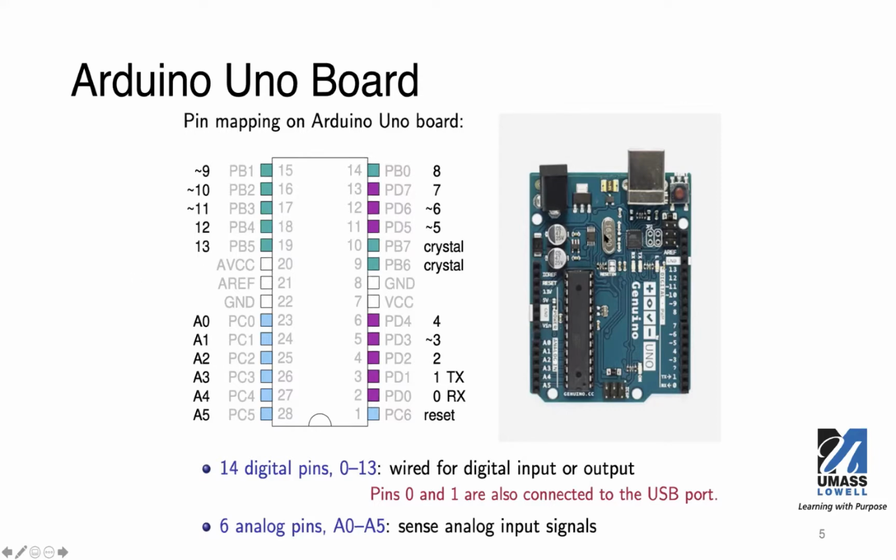For the ATmega 2560, it's a larger board and uses a different processor, still from the same AVR family, but the pin numbers will be different and the connector numbers will also be different. But the way to use them is very similar. They have pins grouped in ports for either analog or digital purpose, and then you can configure them and connect them individually.